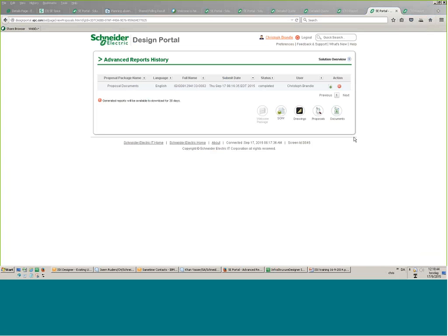We have a question from Yama. Can the airflow control be used with any cooling unit? Yes, with any which is released right now. All the units which we have right now, we can. But if your customer has the ACRC 103, the old 300 millimeter, then the very old ones cannot. Then we need to see which CPU and which firmware. But the new ones, all yes.